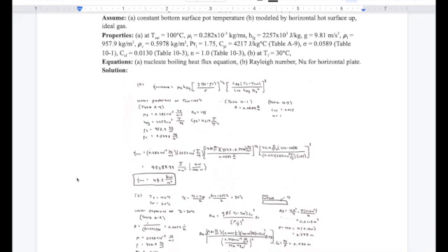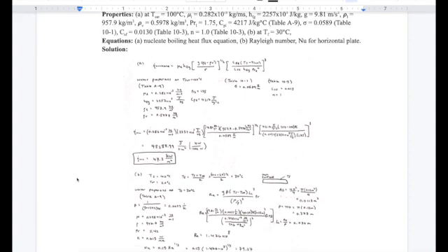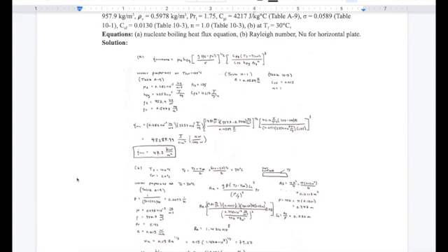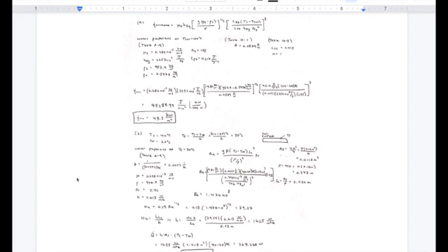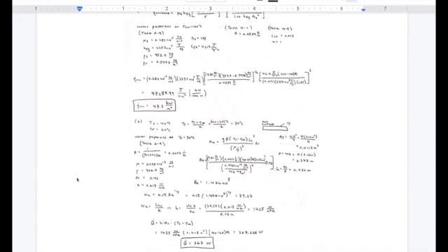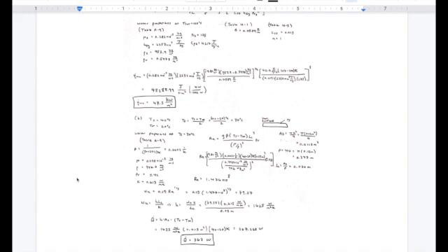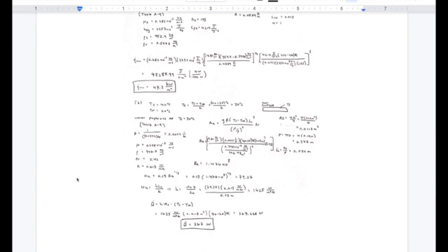In Part B, you see that you are allowing a horizontal hot plate with water properties to cool, so this is natural convection, which is learning outcome 7C. The film temperature is the temperature at which you get the fluid properties. After finding the Rayleigh number, you use the correct Nusselt number equation and then can solve for the heat transfer rate after calculating the convective heat transfer coefficient. For this part, Q is equal to 367 watts.